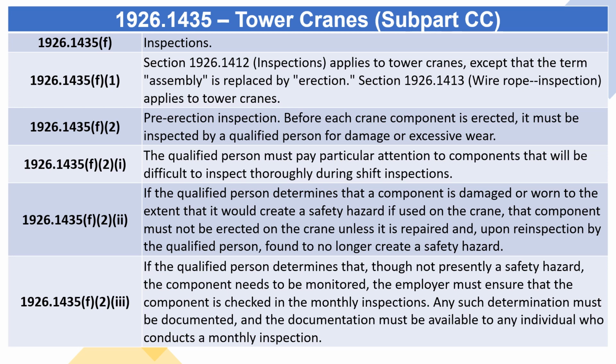1926.1435(f)(2) Pre-erection inspection. Before each crane component is erected, it must be inspected by a qualified person for damage or excessive wear. 1926.1435(f)(2)(i) through (f)(2)(iii): The qualified person must pay particular attention to components that will be difficult to inspect thoroughly during shift inspections.